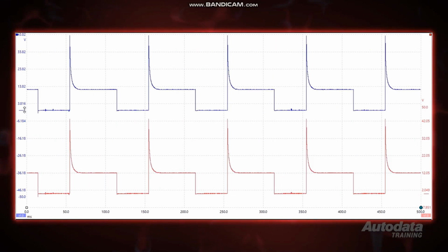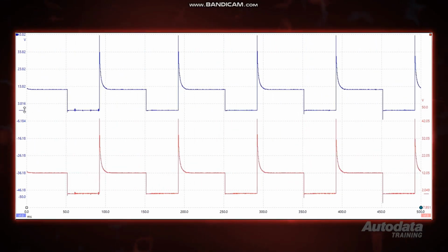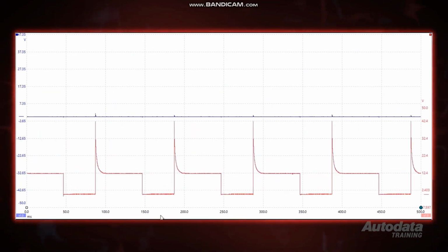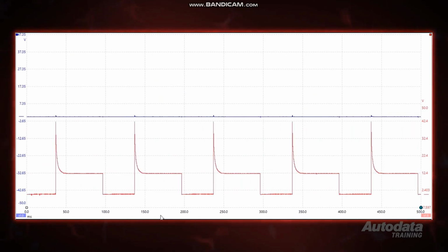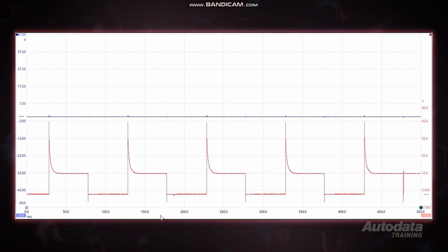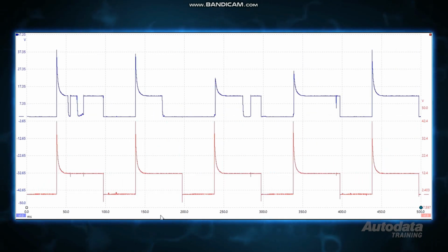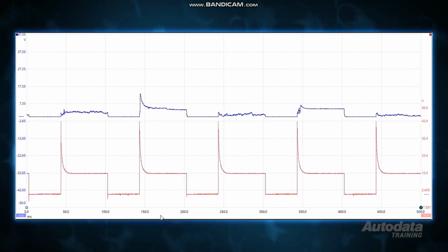This signal pattern can be overlaid and any differences in the pattern can be observed. If the first channel displays 0 and the second displays the correct pattern, then there is an open in the circuit between the two connectors. If the first channel has a lower output voltage than the second channel, then there is excess resistance between the two connectors. As always, repeat these tests at any other connector in the circuit to isolate.